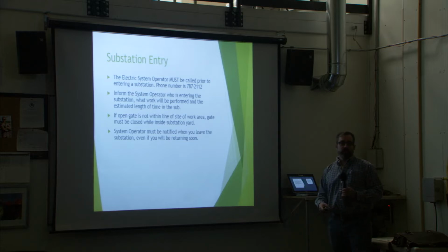This is important because it's similar to the power plant. If something were to happen inside that substation, the operator has a roster of who's there. For one, if you don't call them when you enter and something happens, the operator has no clue you're there. And two, if you don't tell them you're leaving and something happens, the operator is going to immediately be trying to get a hold of you to see if you are in the sub still, to see if you're injured or incapacitated in any way. That's why it's important to let the operator know that you're in the sub.